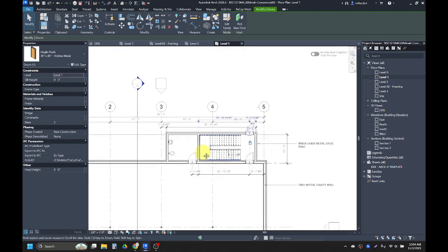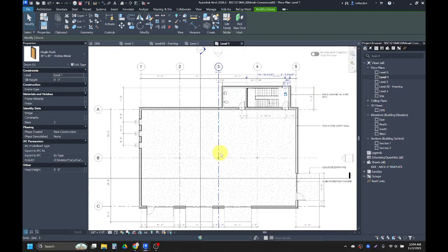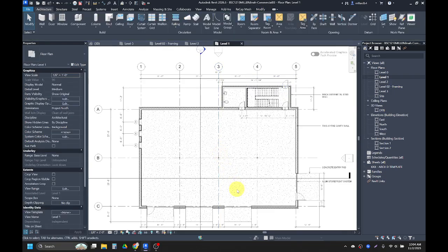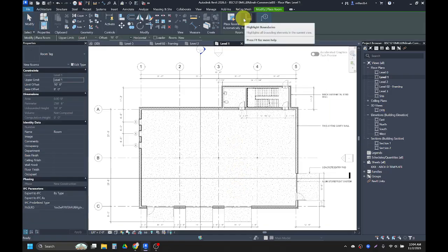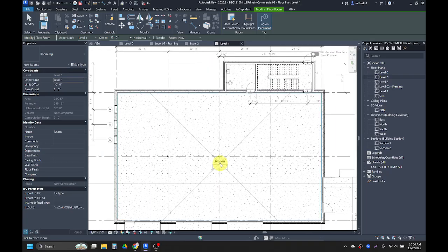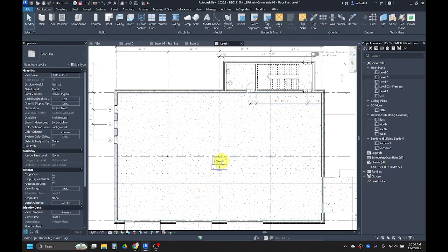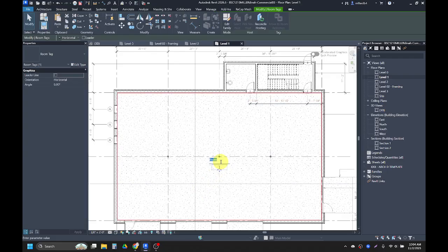Now, additionally, in this view, we've got a room tag, which is tagged differently than with the regular tag tool. So that is this button here, or keyboard shortcut RM. And we can have it where it puts the tag in there automatically. So it's recognizing where the walls are of this room, and I can click to place. I'll hit escape a bunch, and then I can click on that room tag and I can change what it says. So I'm going to call it lease space 101.